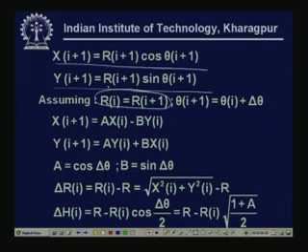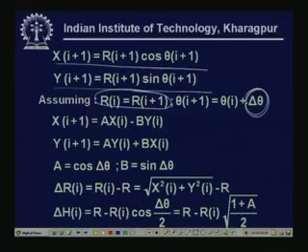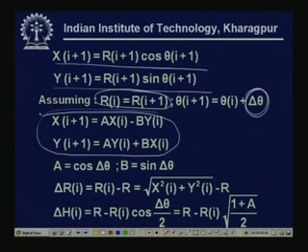And suppose these segments over which we are generating trajectories move by a constant angle delta theta. Then we can easily show that this becomes a linear relation, that is xi plus 1 is given like this, where a is cos delta theta. This is just the cos a plus cos b formula, and b is this.